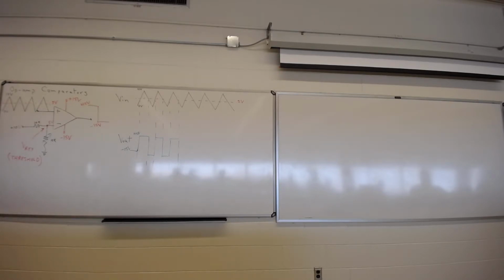Inside of that little chip, the 555, there are a couple of comparators, and that's what they do. They watch a capacitor, and when the capacitor hits a certain voltage, bang, they turn on the output. And then when it falls below, they turn it off. So that's your basic comparator. Now this is a very, very simple comparator, and it's got a couple of little problems. It's got one little problem in particular.